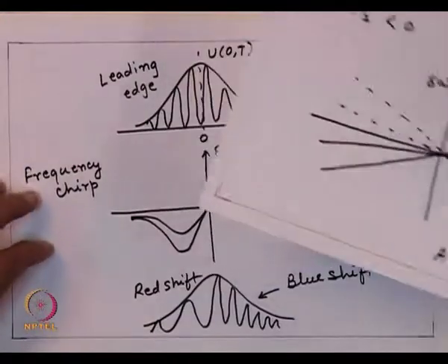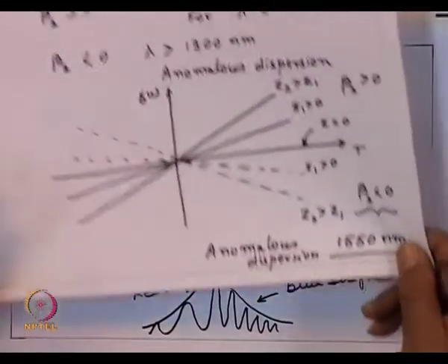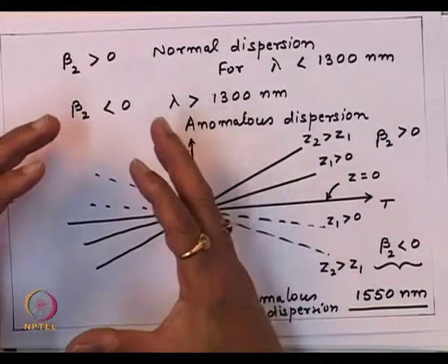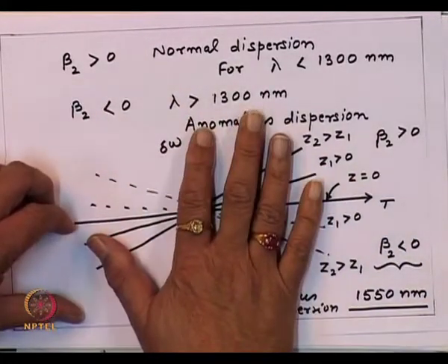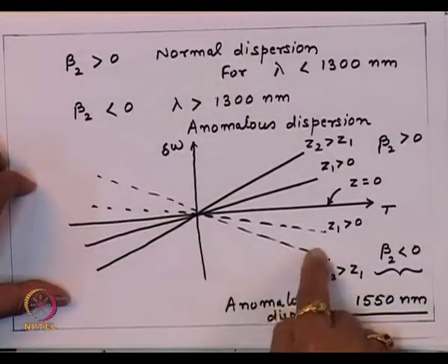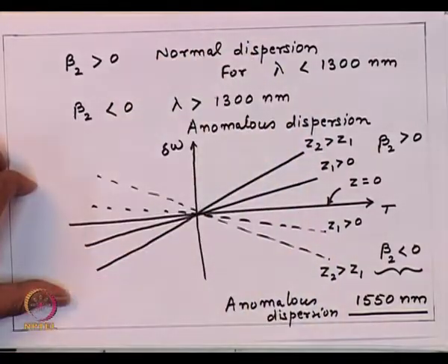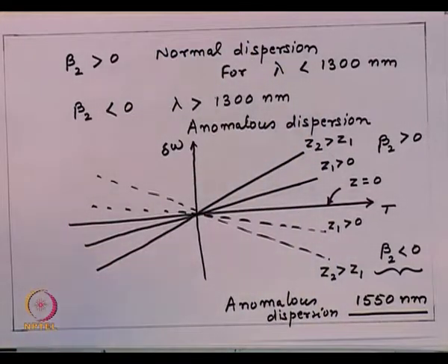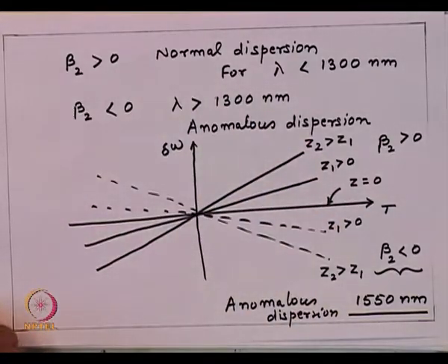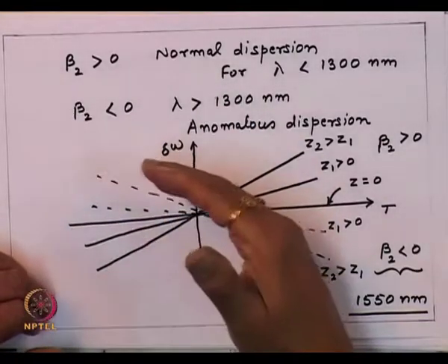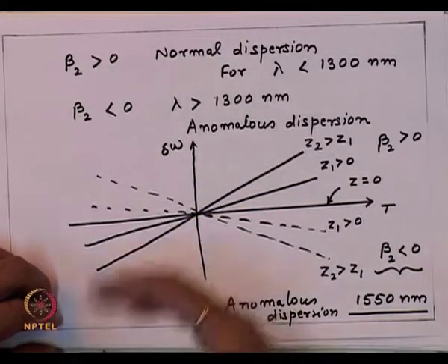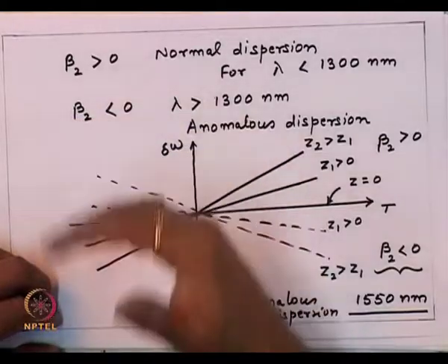Now, imagine a situation that the pulse broadening which was taking place inside the optical fiber because of dispersion was primarily due to this frequency modulation which is created because of the dispersion phenomena. So, the pulse shape modification which you used to see is essentially because of this chirp which is created. So, if the chirp was not there, the pulse broadening also would not be there.